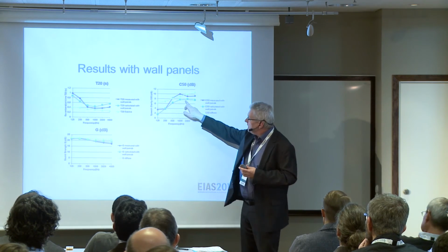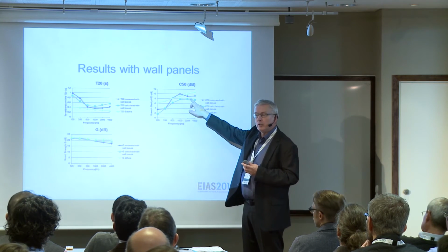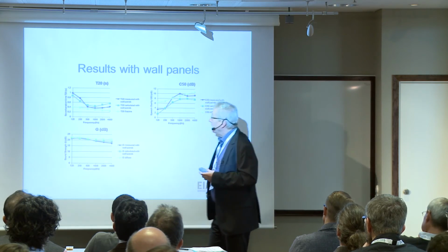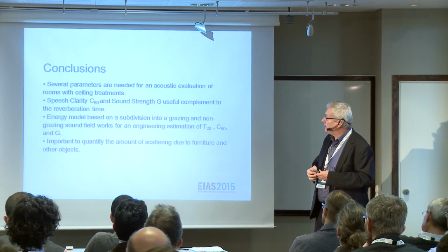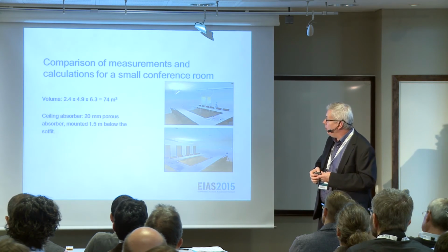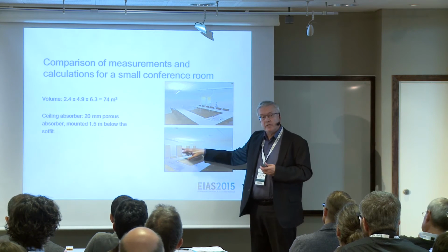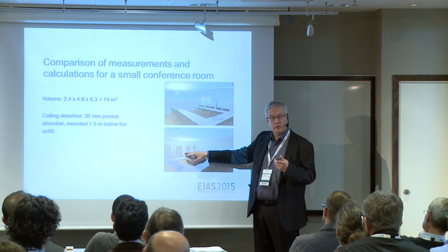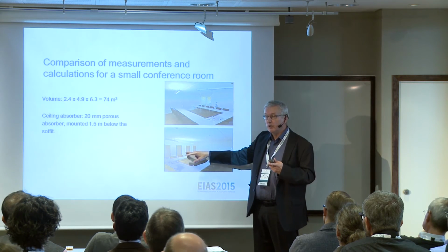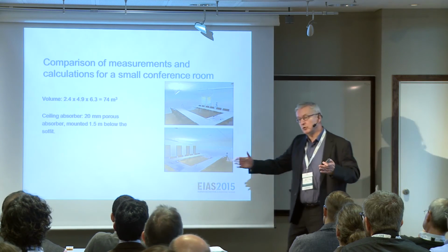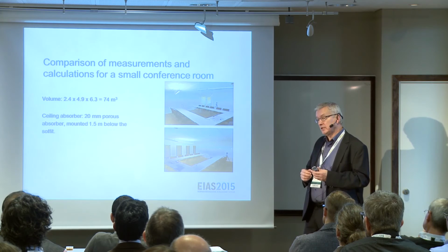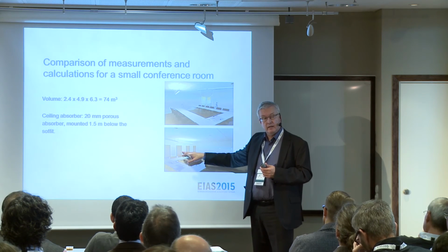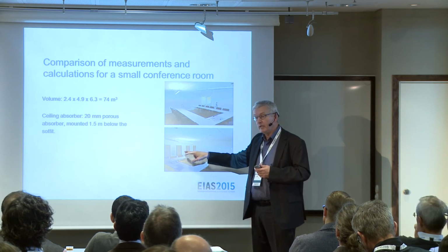But I think it's quite interesting that you see that the calculated strength here is a little bit lower than the measured one, and the reverberation time a little bit higher. And I believe that depends on that when I calculate the absorption for the wall panels, I have used the absorption coefficient measured according to ISO 354. And you know that if we measure on large spaces or small patches, that will make a difference. So I think this is a little bit of an area effect that we see. But that is something we can compensate for, taking the area into account.